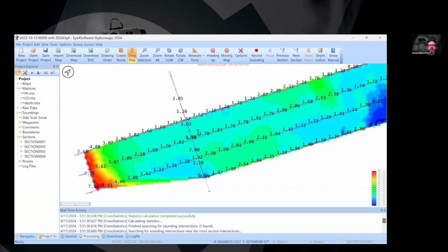Question from Mark. We have tested an Echo Sounder from a drone and compared it to our multi-beam Echo Sounder data, and have found that since there is not a GNSS on the Echo Sounder itself, and it was utilizing the corrections from the drone, since the cable holding the Echo Sounder is not rigid, it could be affected by water current and drone movements. We already discussed that.